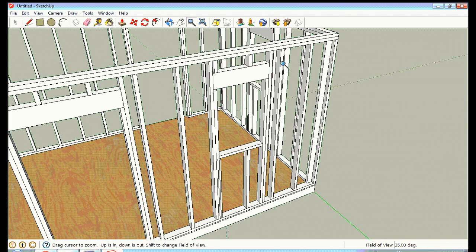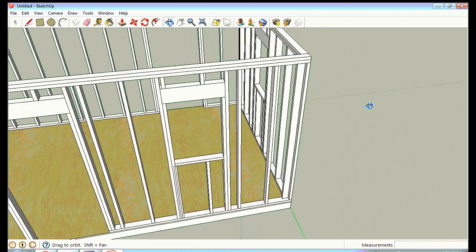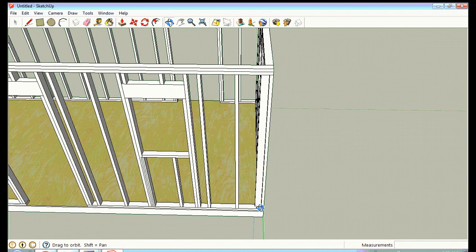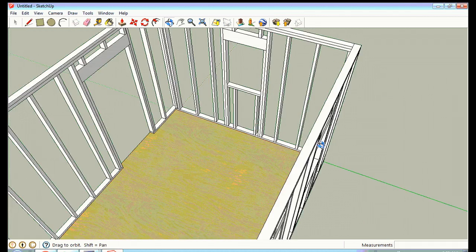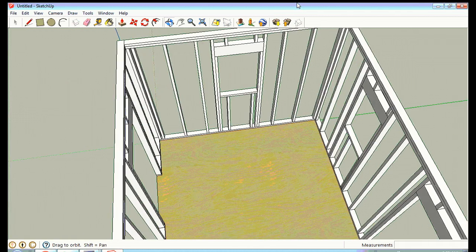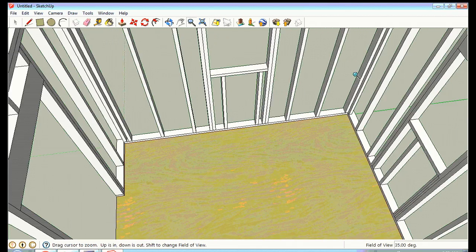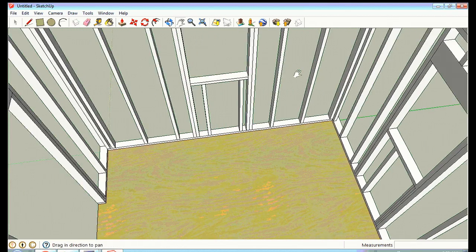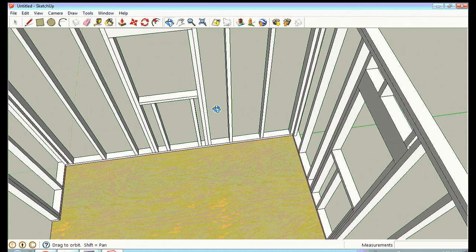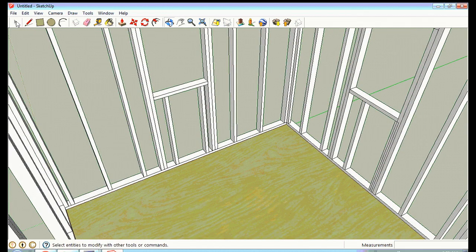The reason they use it is because now you can see I can put a full bat of insulation in here and just tuck it right up against that 2x4, and that way it seals this so I don't have that little 1.5 inch space. That is a nice way to do a corner, and it still gives you even more of a lip to attach your drywall to. You can see from the inside, now I've got a nice wider lip to attach my drywall. I'm going across here, I can screw it to this lip.